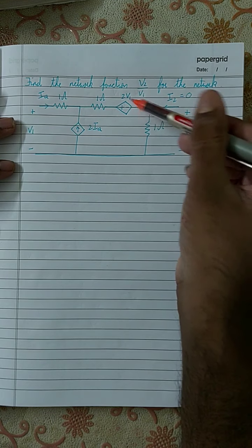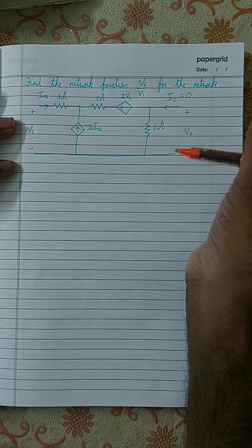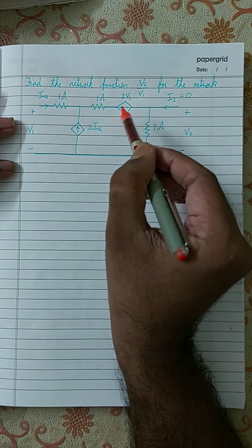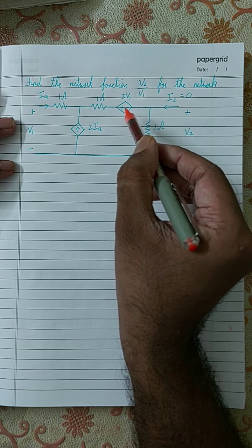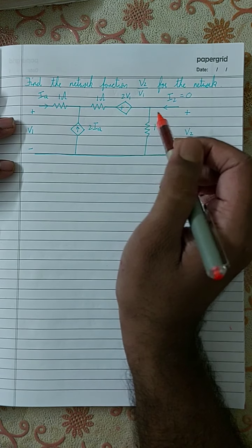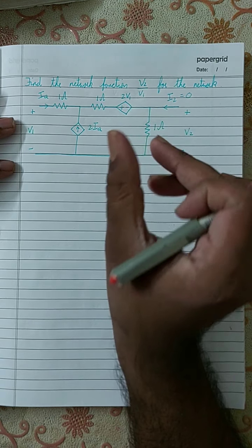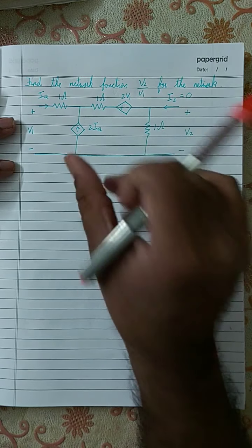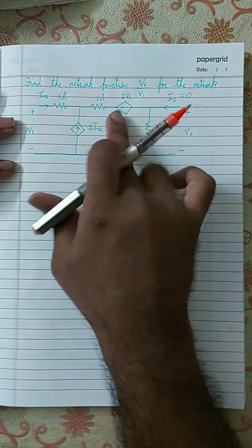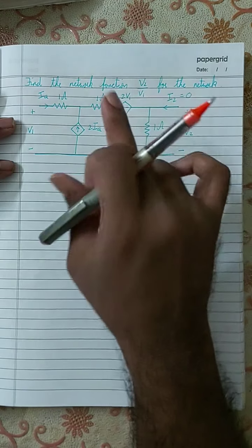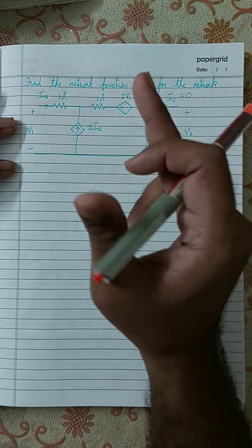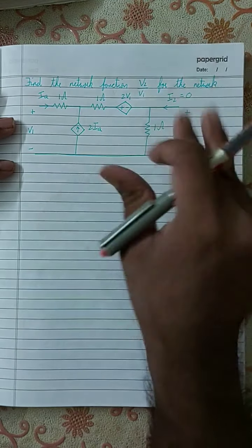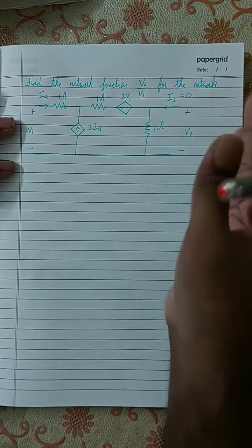One interesting thing about this is that there is a voltage source in between two nodes. We all know the name of that: if a voltage source comes between two nodes, then that pair is called a supernode. So that is what you see here. If you see a supernode, then you cannot write the node equations; you should write the supernode equations. That's the only difference, just like how you write supermesh equations.